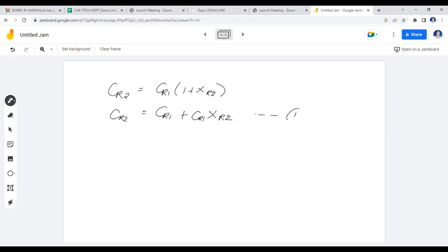Let's say this is our first equation here. What is our CR1? Remember, there is some R formed already in the MFR, and there is no initial concentration for R. So our CR1 would be 0.002. That's correct. As for this one, we can have CA1 XA2 based on stoichiometry over 1 equal to CR1 XR2 over 1 as well.